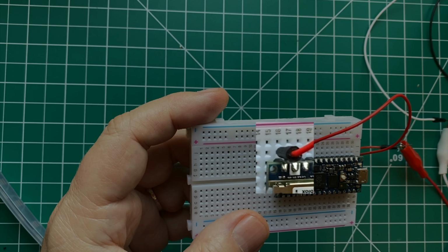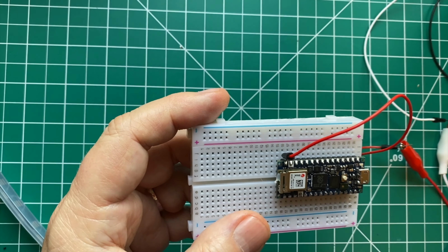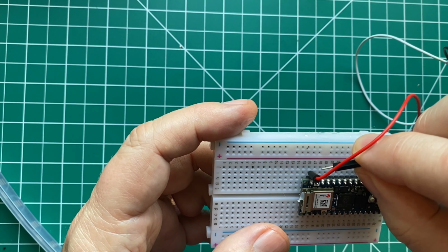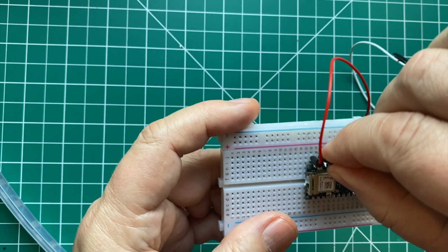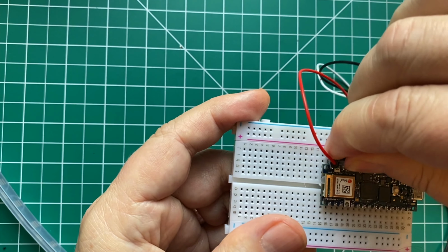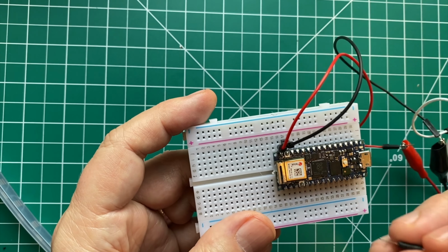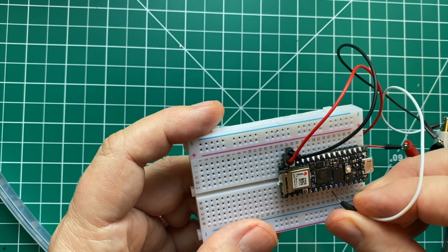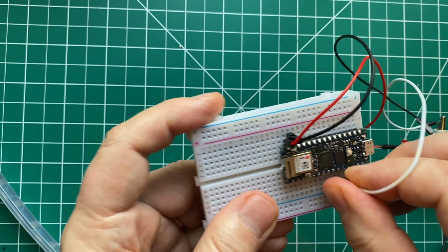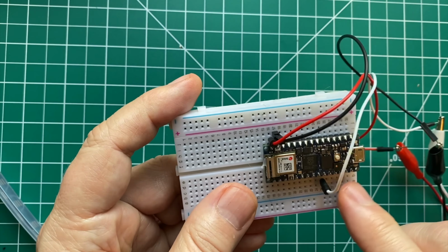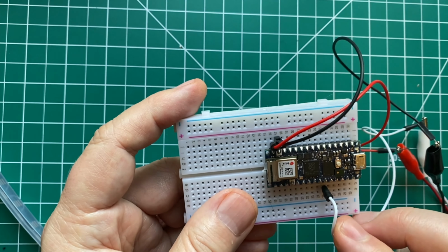Then the pin next to that is highlighted in white, that's ground, so I'll plug my black jumper wire into that column. Always take extra time to make sure that you're never going to plug power and ground into the same column. And finally, my white signal wire is going to go into D7. That should be this column right here, and you can count over from the right just to make sure that you're getting the right column. And with this, our wiring should be correct.